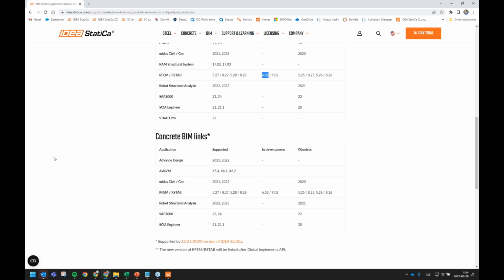Okay, there was one interesting question: can the member type VYVZ be used for pinned connections too, or only for bracing? Well, I would say that for pinned connections, it must be used. So whenever you have a connection with one bolt, you always have to change the member type.